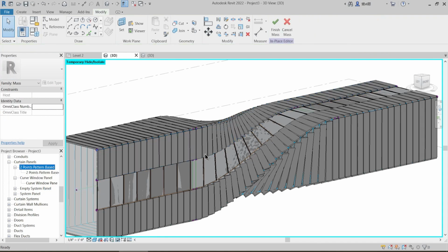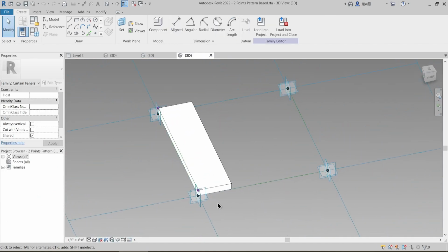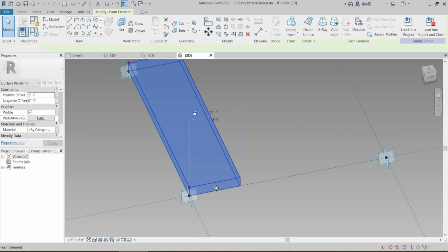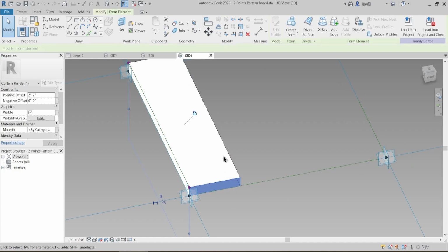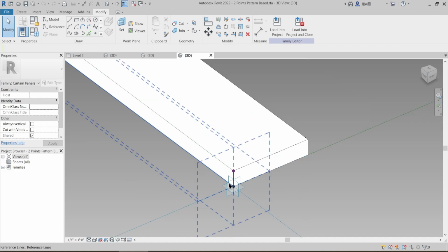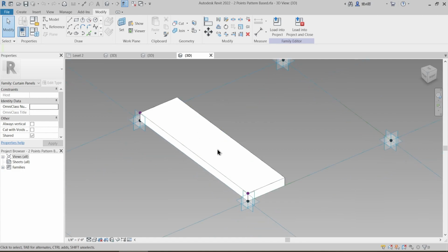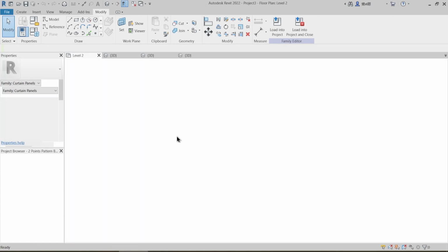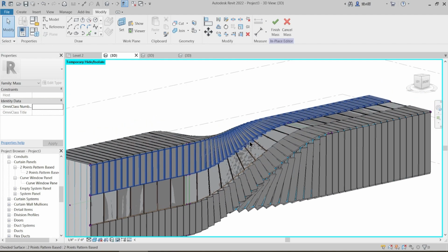Just edit type, and from 1 to 2 you can just actually dissolve this and lay a point over here somewhere, 0 point, give it a normalized curve parameter 0.9 and this to be 0.1, and then extrude this surface and then load that back into the project. So at least these junctions will be all right.